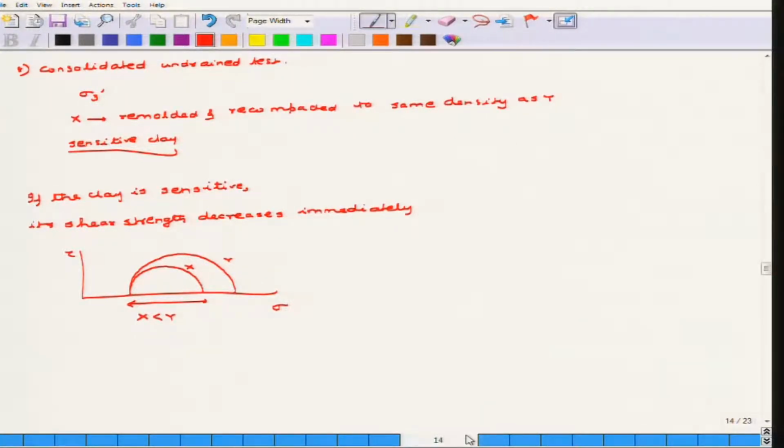Now, this third problem basically has a little bit of mechanics concept rather than considering all this Mohr-Coulomb failure conditions. So, in this case we will find out how, with the help of our triaxial test, you can find out the Poisson's ratio in case of a triaxial test, and then you can link it with the consolidation test Poisson's ratio.